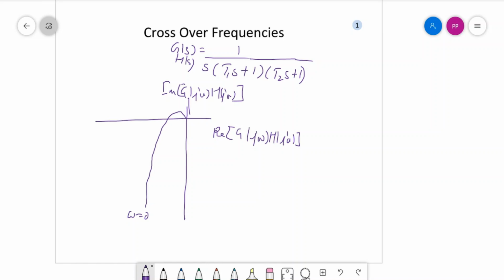So we can draw with this center and radius 1 an arc which will definitely cross this plot, omega equal to 0, omega tends to infinity. So at some point, for a stable plant, we'll get that the crossing will be in the third quadrant of the polar plot. So this point will give a length of radius 1, this is of length 1.